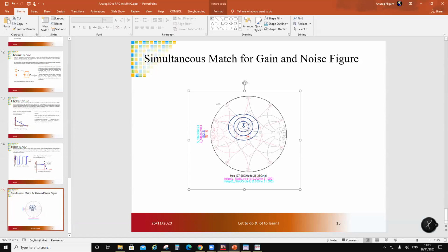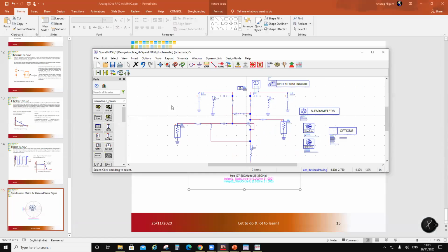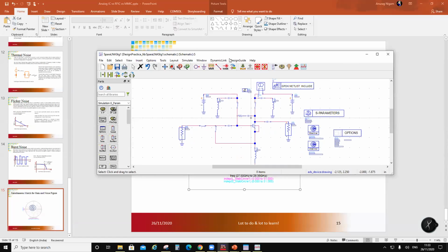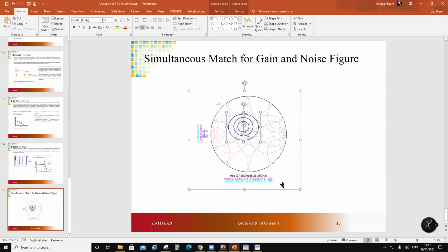It is very simple. I would go here and introduce the inductance here, and I'll keep on increasing the inductance, and you can do the maths also. What you do is you can calculate the inductance which causes this impedance to look like 50 plus j something, and then the negative reactance part you cancel out with the matching. So that way, this circles. So right now, let's just put it over here.